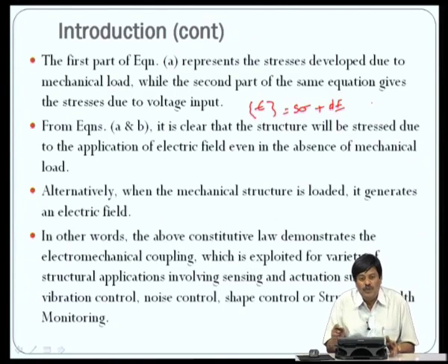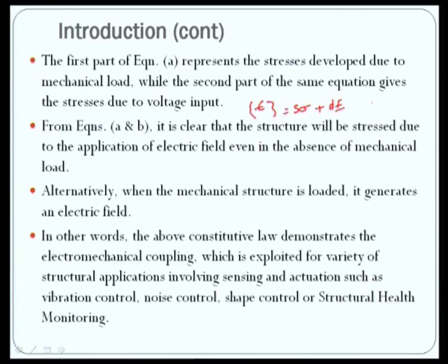So, we can actually use these additional terms in our actuator application or sensing application. In other words, the above constitutive law demonstrates the electromechanical coupling, which is exploited for a variety of structural applications involving vibration control, noise control and health monitoring.